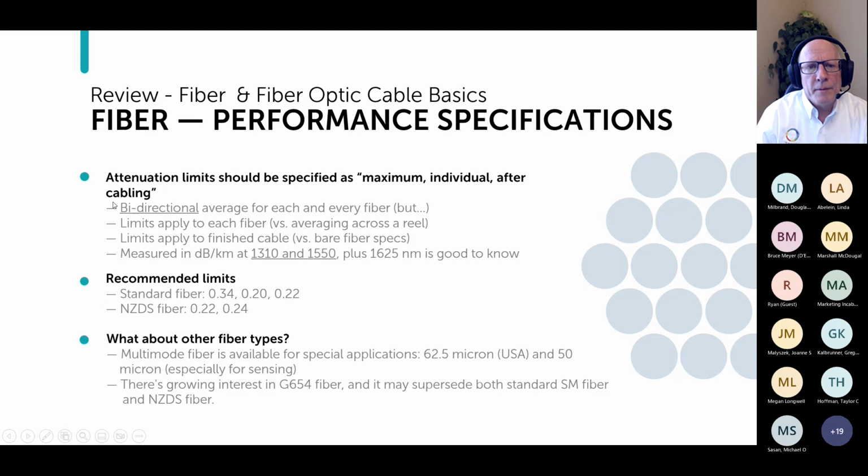So let's jump back up because I kind of skipped over bidirectional. Bidirectional means you're measuring from the outside end of the cable and the inside end of the cable and then averaging the results. I'm a lot old school, and I think that's the best way to do it. And for OPGW, that is still my recommendation for doing it. Dielectric cables, the industry has shifted more to doing outside in testing only for practical reasons.